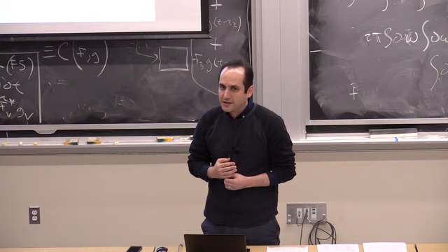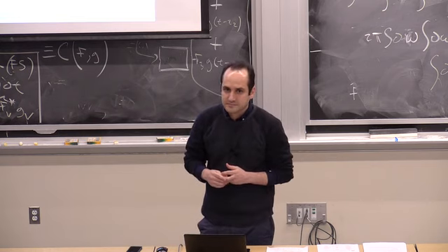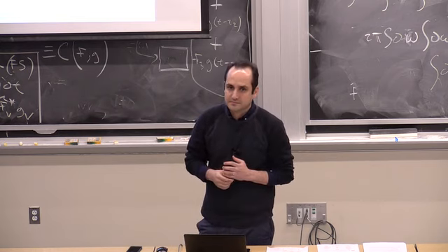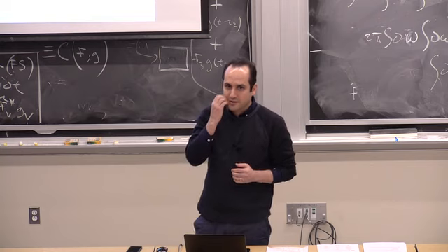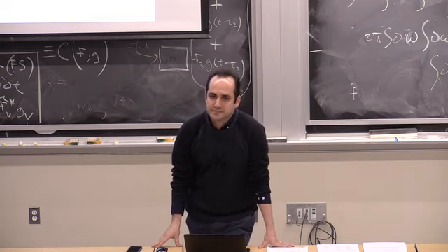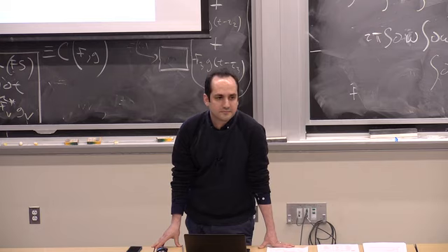Right. Just like, I have a question. Why do you think that the balanced load will require more vehicles? I tend to believe that it's actually somewhat more efficient, capacity-wise, than the alternative. But why do you think that it has more vehicles? Because the frequency is higher. So. Right. It's higher only at certain points. You have to have enough vehicles to cover however many simultaneous trips. But what Ian was saying is you can't cut service so short that you don't meet those load factors. So in the end, you end up using more vehicles.